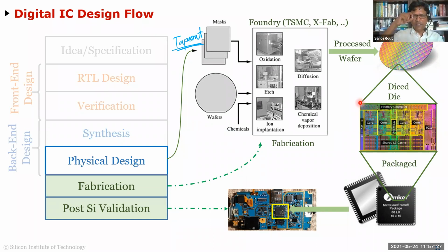So you take fine wires, gold wires or copper wires, and you connect them to the lead frame, and the lead frame is these leads here. These are much bigger, which you can put in the PCB, and maybe I'll show you a picture later on sometime to show you that. Okay, so you put it on, and that's how it gets connected to the outside world.